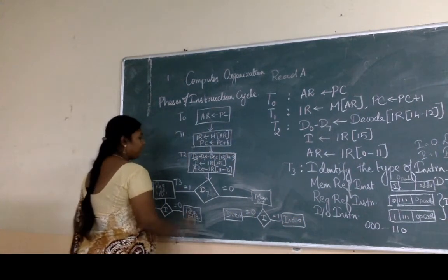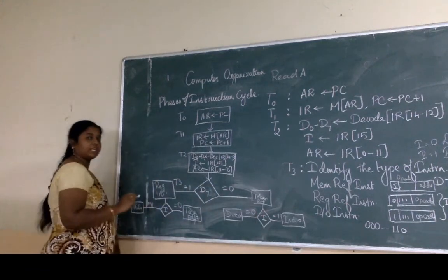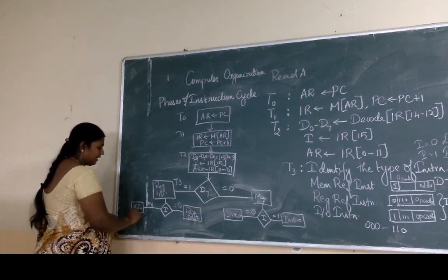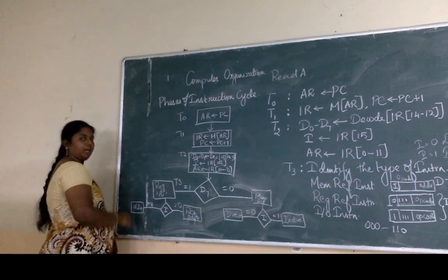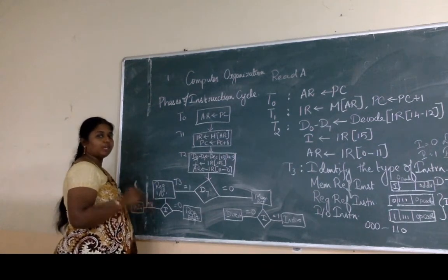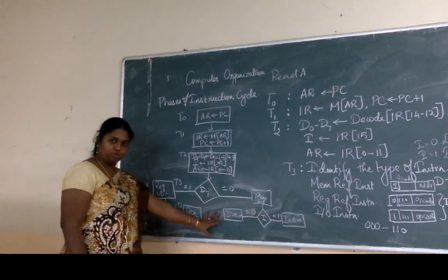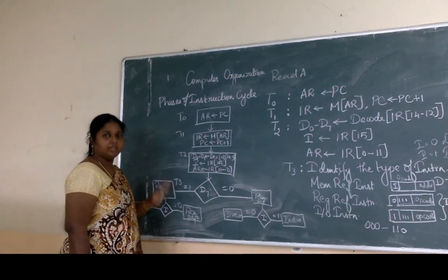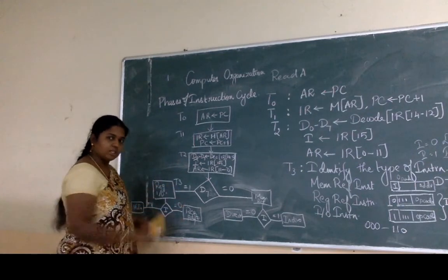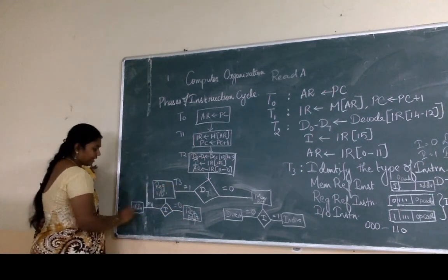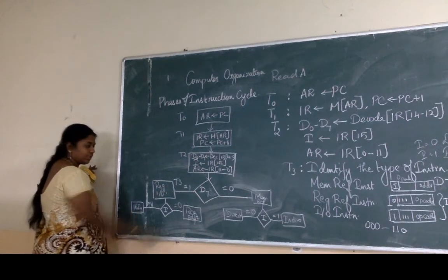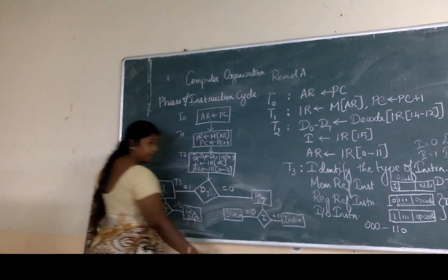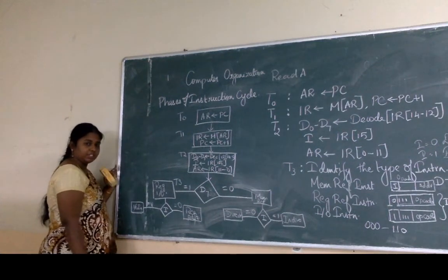So I am going to perform all of this checking at time cycle T3, and at time cycle T3, I have to start executing something. I have decided what to do. Now I should do something. I have not done anything at time cycle T3 yet. I am just looking up some values. At time cycle T3, I can start with the execution of an IO instruction, or register reference, or direct memory access, or an indirect memory access instruction.